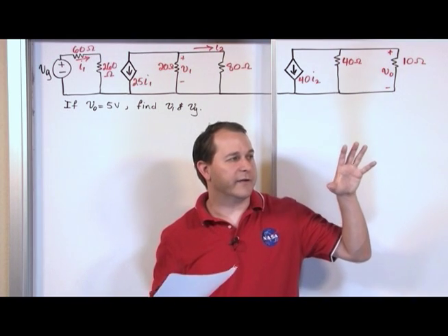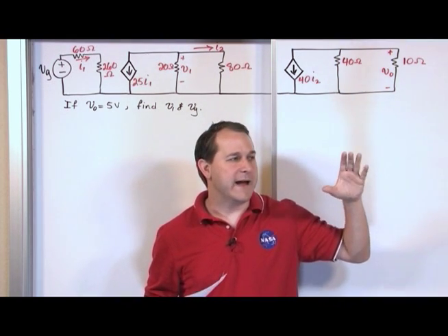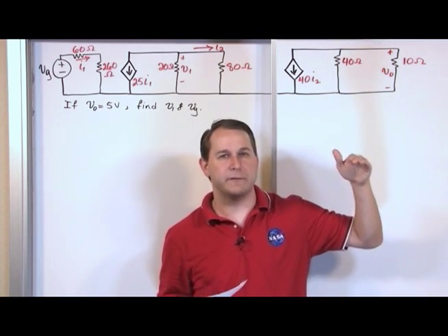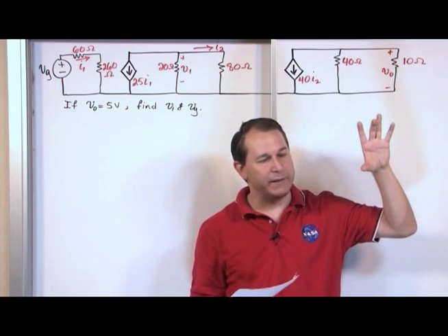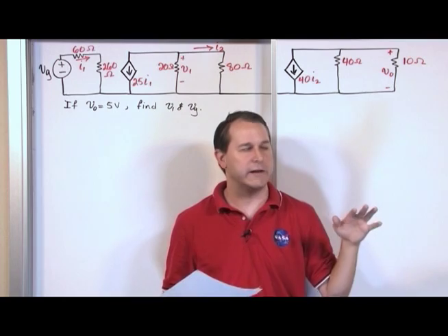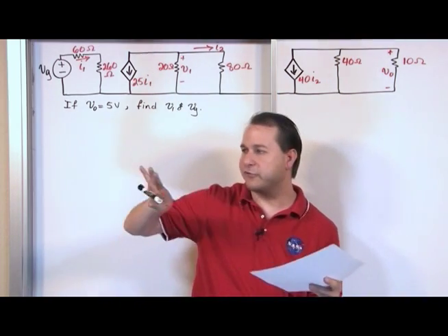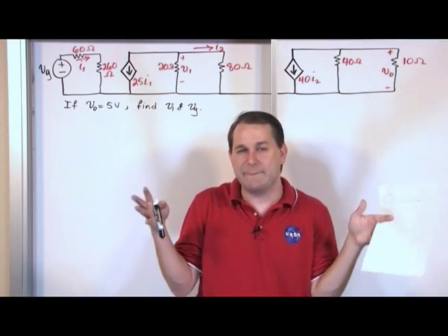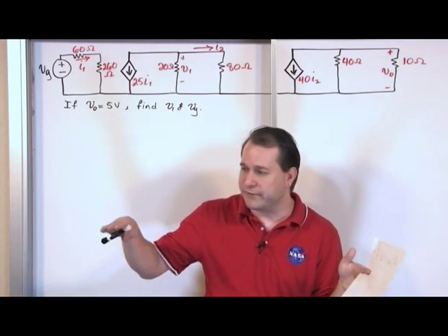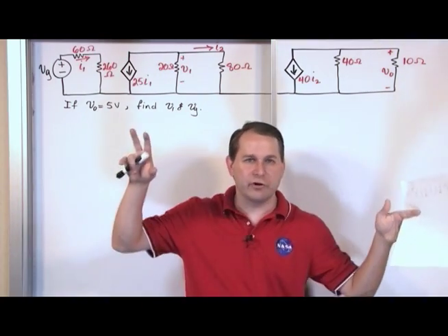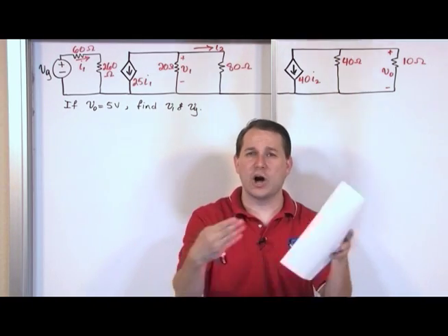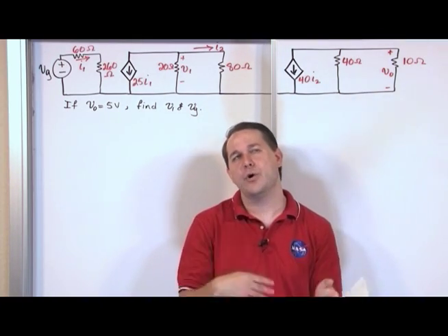If you have a very high voltage circuit over here that instead of 0 to 100 volts, maybe it's operating from 500 volts as a base voltage to 600 volts. The difference being still 100 volts, but its base voltage is floated up, so to speak, as we usually call it, up to a higher level. And then you have a circuit element over here in the same physical box, and he is operating properly from 0 volts to 100 volts. Well, then you've got two circuit elements, the base voltage of which are different. And so that can actually cause big-time electrical arcing. So I hope that analogy makes sense.